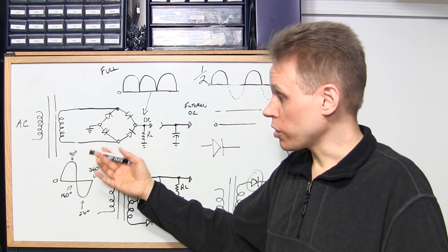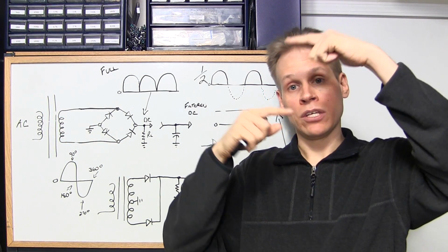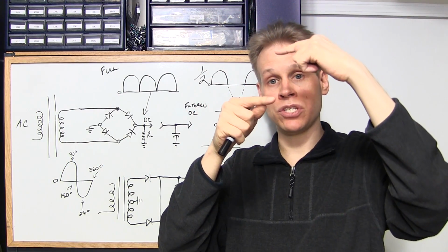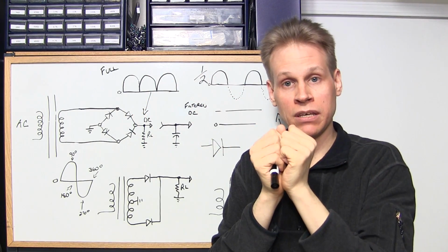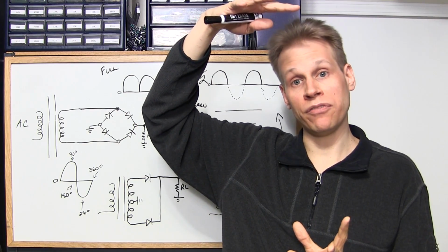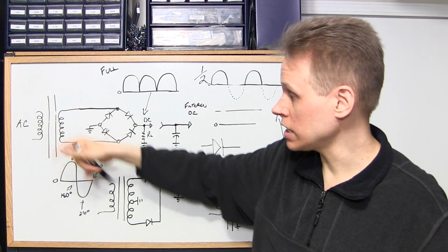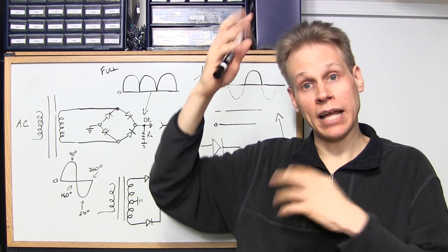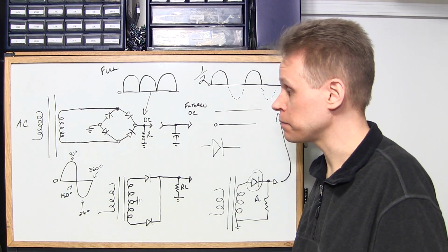So how a transformer works really quite simply is as this is oscillating, as it's changing, all right? So we have positive here, negative here, say up here and here, okay? And it's changing, okay? It comes to zero, all right? So basically the magnetic core on the transformer is collapsing. And then, of course, this is changing direction, so we get a rise again on the field. Now, as the field on the transformer is rising and collapsing as this is oscillating, the rising and the collapsing of that magnetic core is inducing a voltage in the secondary winding.